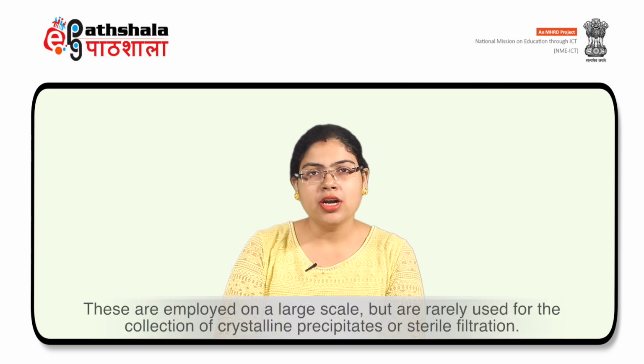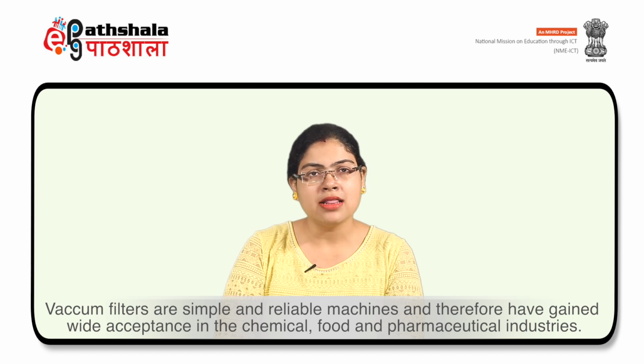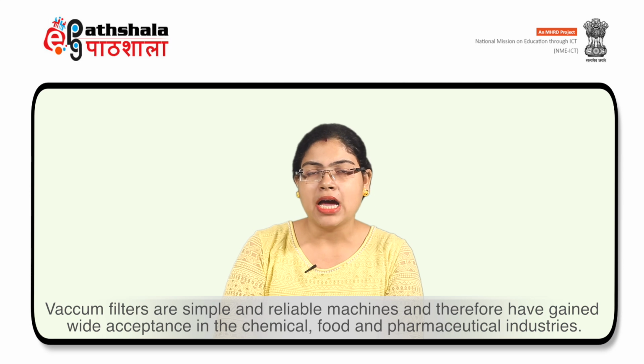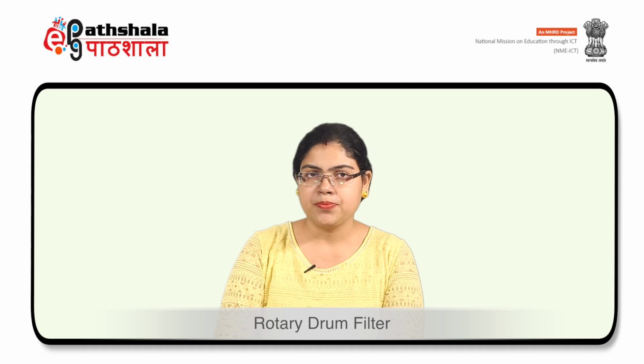Now secondly come to vacuum filters. These are employed on a large scale but are rarely used for the collection of crystalline precipitates or sterile filtration. Vacuum filters are simple and reliable machines and therefore have gained wide acceptance in the chemical, food and pharmaceutical industries. Under this, we will discuss the rotary drum filter.